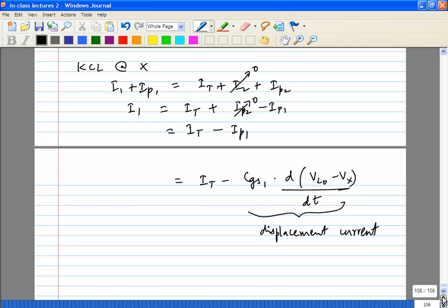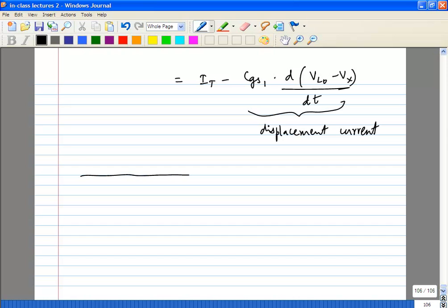And what will the signal at node X look like? That you already know, right? It's going to have all the even harmonics. It's going to look something like this actually. Ideally you want it to be flat. If your LO signal was a very small signal, it will just be the bias. It will be input bias minus VGS of the input transistors, but that is just a DC. If you have a larger signal at the LO, in this case we do, then you will have all the even harmonics coming in at the common node. It looks something like this.